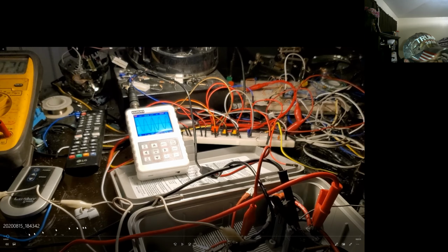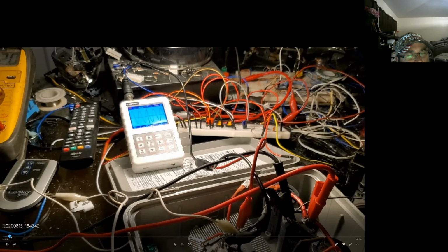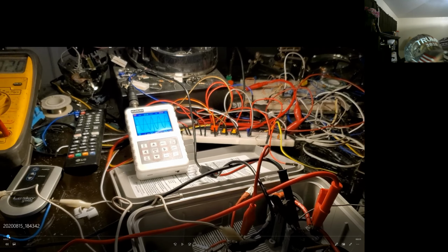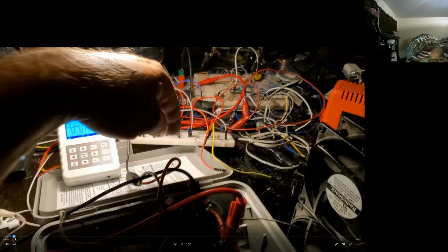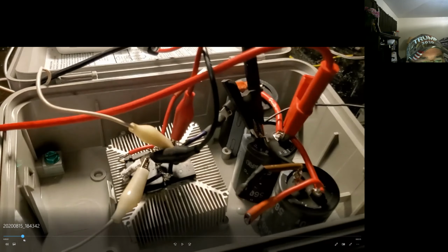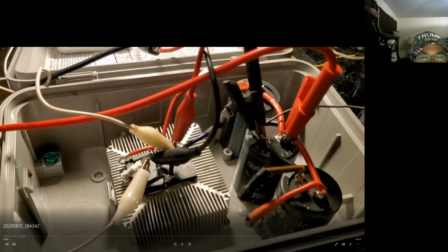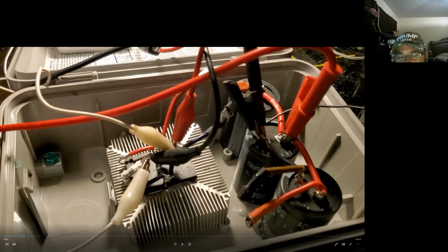So yeah, let me fast forward here. I was hooking up my little scope. My old school scope was getting all sorts of noise, so I brought in that cheap Amazon one, and it actually works. But right here it is. This is 2 bridge rectifiers I took off of a big circuit board that comes out of a mini split. So I'm wiring it just like that. Using single phase input, going to the DC bus, which is capacitors, and into the VFD section is exactly what they do.